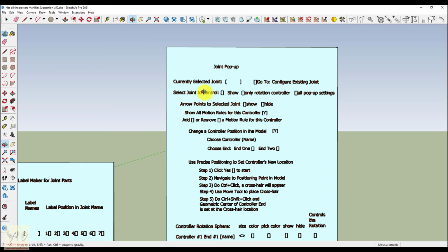One of the things we can do when we select a joint or an articulation and we're looking at the entire model is that we might have some confusion as to where this joint is in the model. So this does this for you. If you click on this and look at your model, you'll have an arrow pointing to the controller that you have just chosen. And by clicking on this, it gives this display system permission to show everything that is associated with that controller.